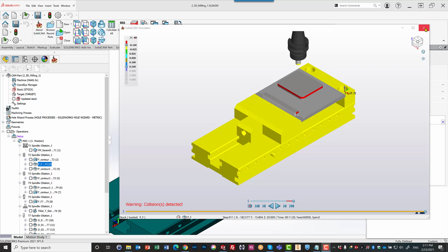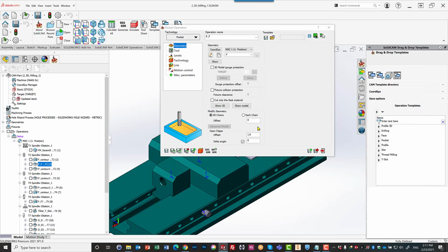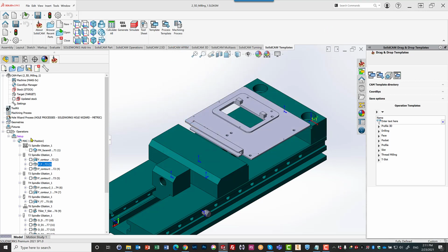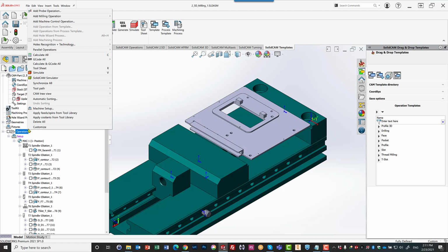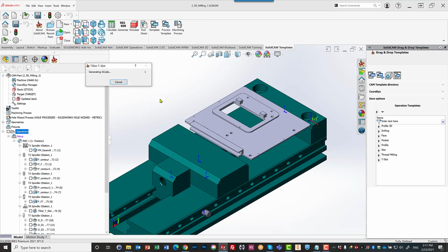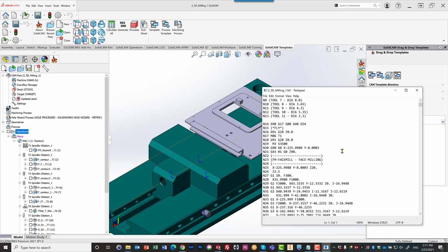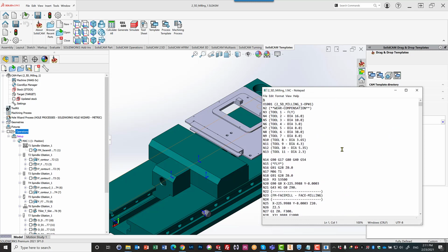Now, just as before, we can also create the G-code as well. Just by clicking on G-code, or I'll just go even out of here and create a G-code for everything. Right click over here, create G-code for all, and I have my G-code for all of my operations done at the Shopfloor edited stage.